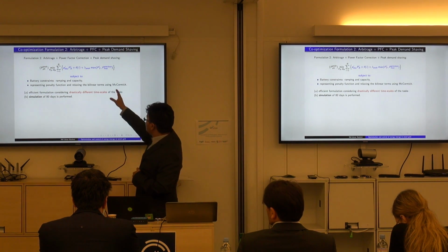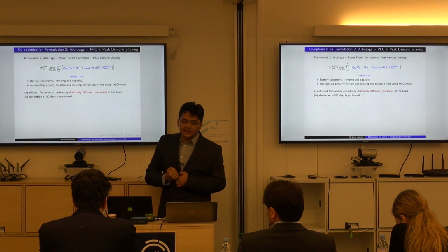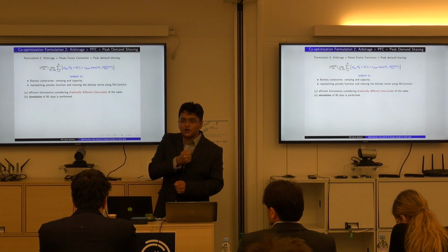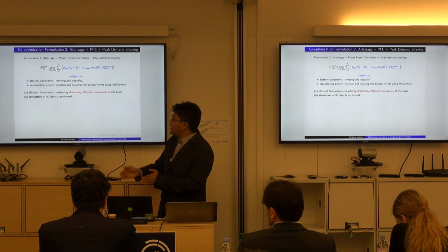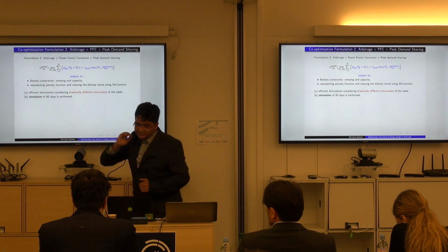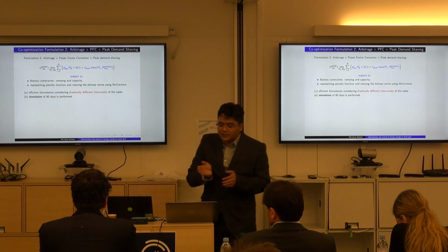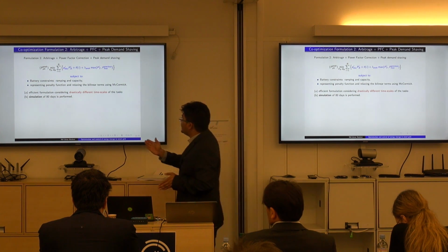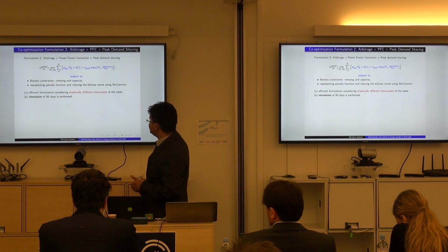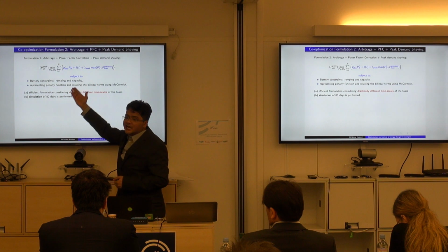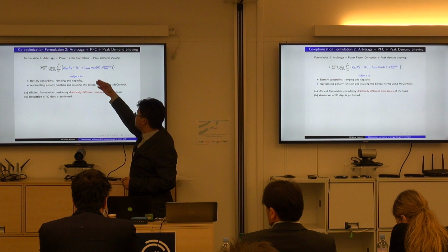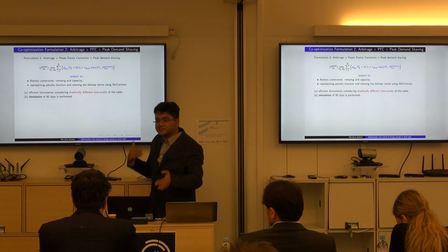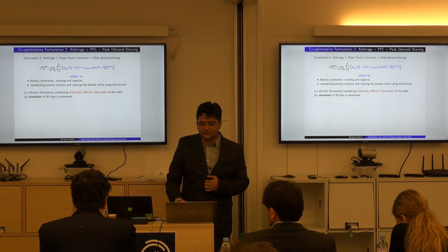So we introduce the concept of a memory variable which captures the peak which has already occurred, and every time an optimization is done only for a look-ahead horizon of 1 day, and this previous max captures what has already happened. If the previous peak is higher than what the consumer is witnessing now, then this component becomes inactive. Using this strategy, we are able to mix these two different time scales in the co-optimization formulation.